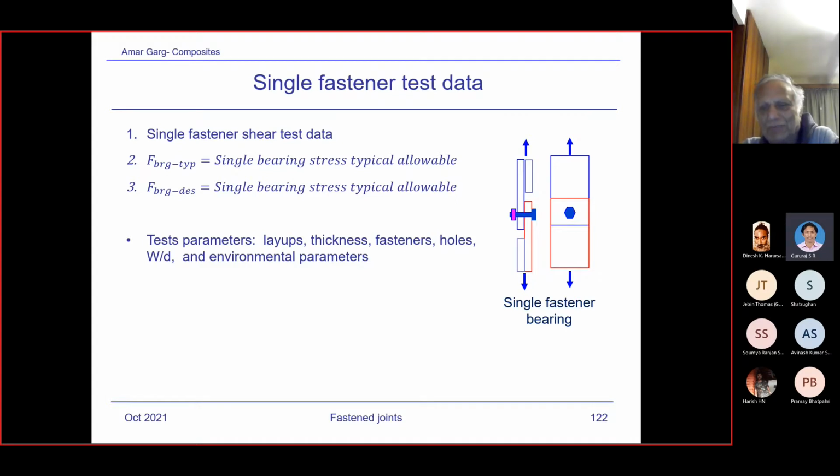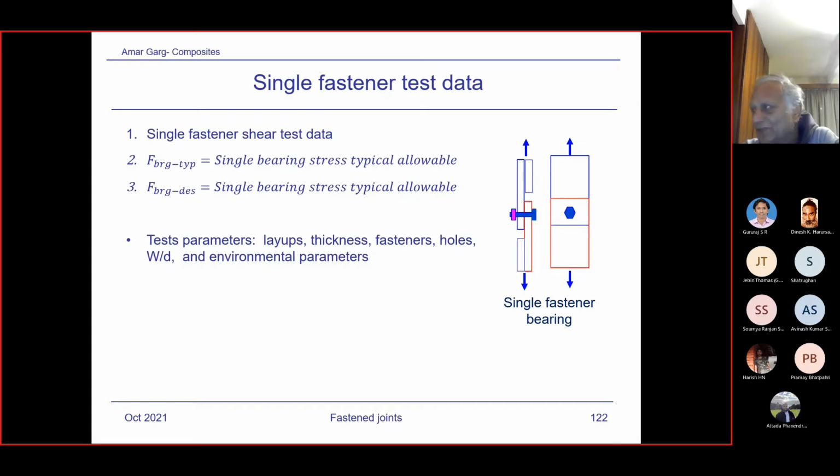Well, these days the process is computerized. Finite element models generate the load for each fastener. So for every fastener, you pick up the load and decide about the bypass based on the procedure. It's a bit involved procedure, so you write it down, put everything in an Excel spreadsheet or whatever software you can develop, and just run everything. That's very convenient. Otherwise, you will be struggling to find which hole is critical, which is not.